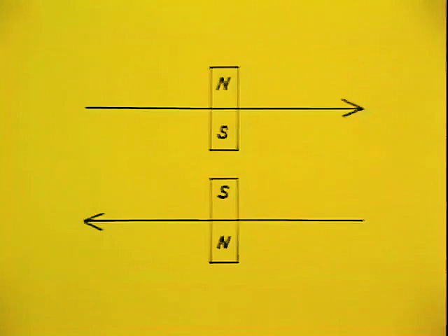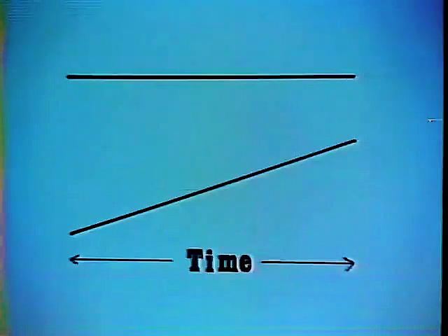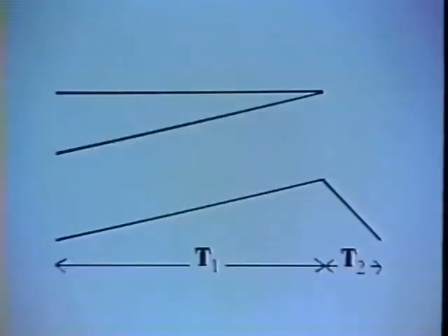The magnetic field deflects the electron beam in the tube, so the coil is oriented around the neck of the tube to a position where it will deflect the beam horizontally. As it changes polarity, it deflects the beam the other way. The magnitude of the current will determine how wide the deflection is. The speed of the deflection is determined by how long it takes the current to rise or fall to its maximum and minimum levels. This is how the retrace is made much faster than the visible active left-to-right scan.